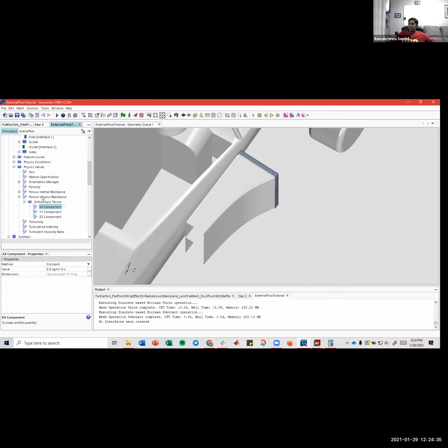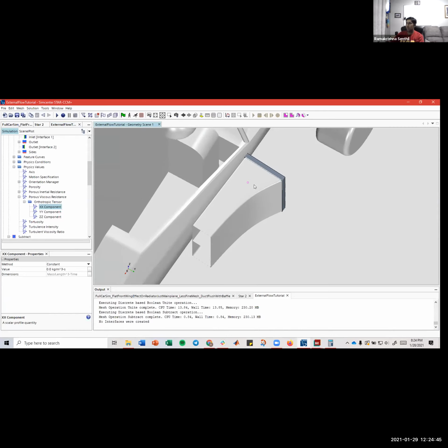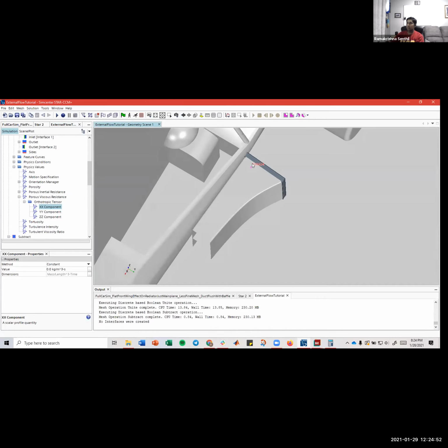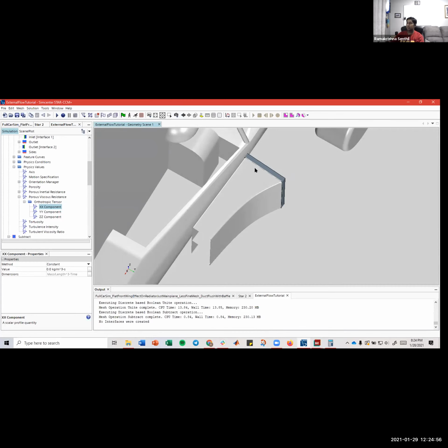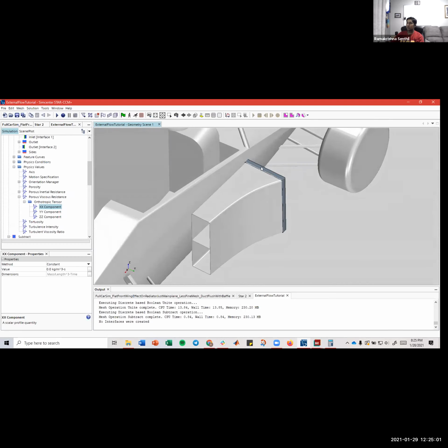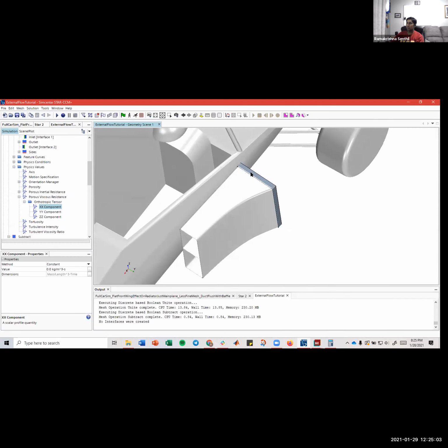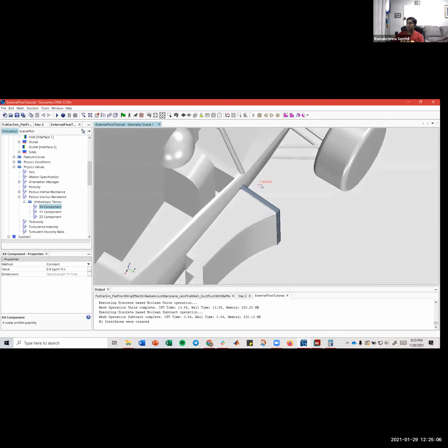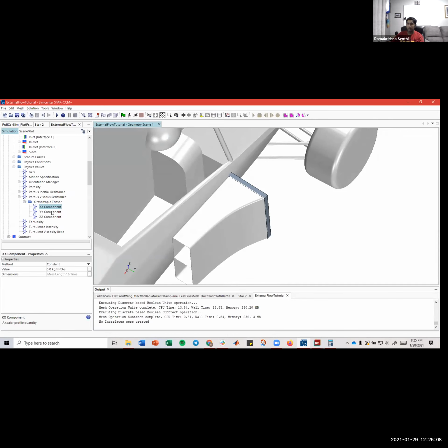We want to change the porous viscous resistance. So basically what this means is, just think about resistance. We want to minimize the resistance in this X direction, but increase the viscous resistance in the Y and Z direction so that airflow basically cannot move in those directions, and therefore all the flow going through this will only have an X component and basically no Y or Z components.